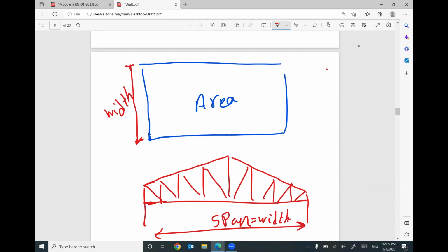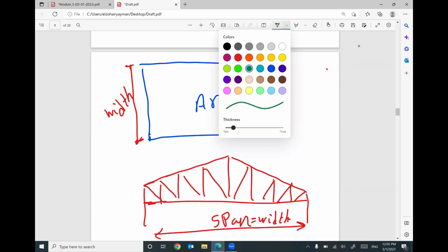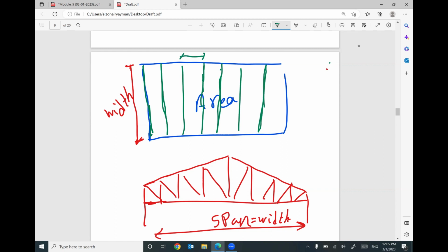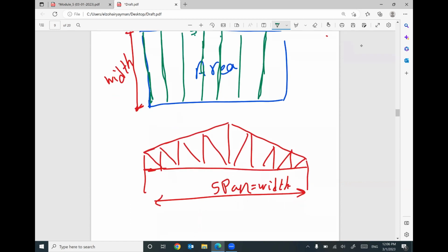I decided to put this main system, or this truss, at equal spacing. Your spacing can be 20 feet, 25, 30, but keep in your mind, we need to maintain equal spacing, which is S. Also, from this truss that you suggested, the horizontal distance is called A, the inclined distance is called A prime. This is the first step.